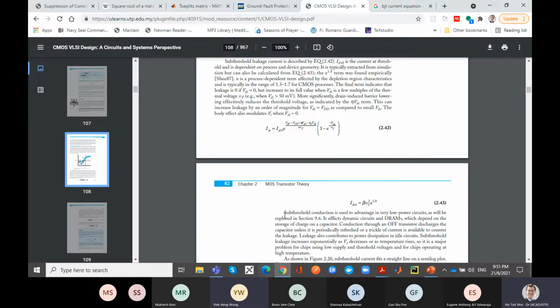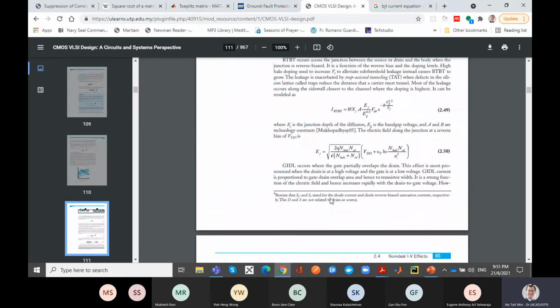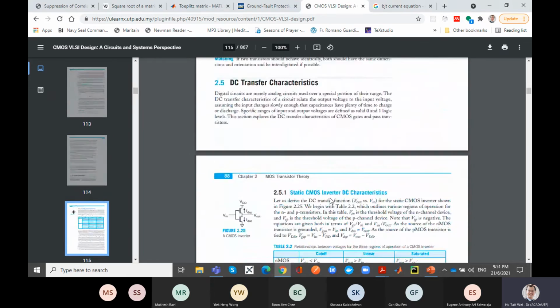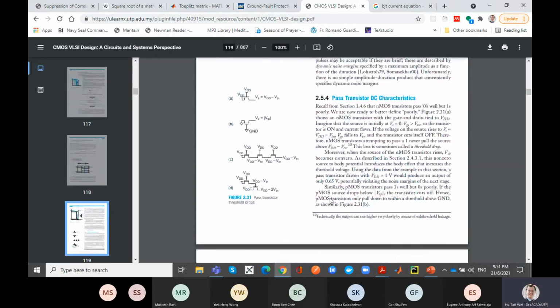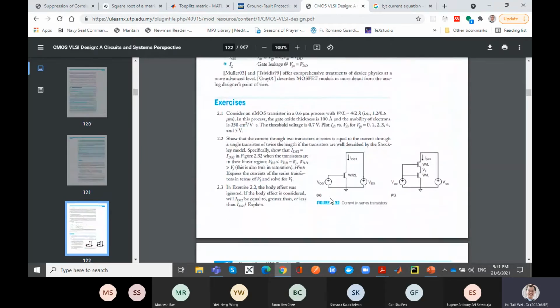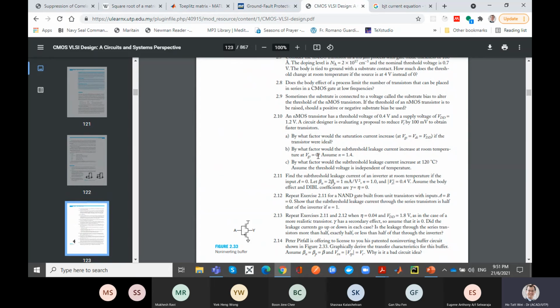Okay, that's just to give you a motivation. Why am I making you do all this calculation? Yes, it's very theoretical and all that, but there is a reason, because I want you to learn how to compute the multiple of subthreshold leakage as a function of the factors. And here, you may see all these numbers, but the key point to drive home is that subthreshold leakage is dependent on temperature.